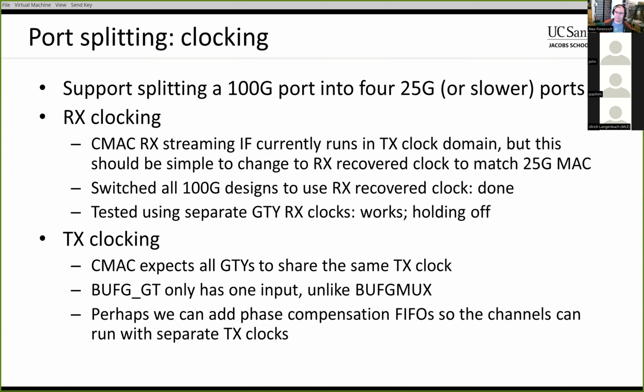Part of this is to figure out the clocking side of this, and I did some tests with the RX clocking. The first thing I did is I switched all the 100 gig designs to use the RX recovered clock instead of using the TX clock. So that's done, and all of the designs in the development repo have been updated along those lines.